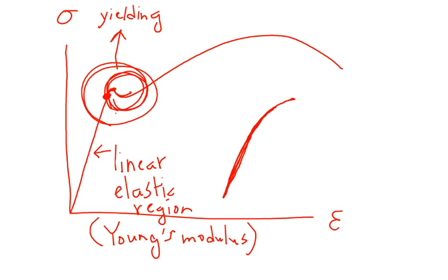Eventually it reaches that peak, then it dips, and it's very difficult to determine where exactly the straight line ends. So what people have found works really well is you just go to where that valley is. After it's peaked and it goes back down, if you look at the very bottom of that dip and draw a straight line across, that usually is dead on as far as where the linear portion ends. The stress corresponding to that is what we call the yield stress.